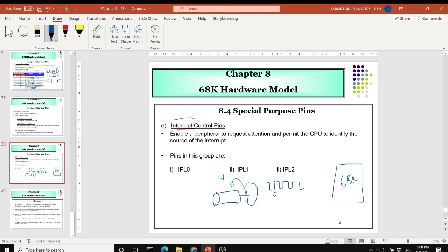One way of achieving this is by using an interrupt. The pulse is connected to the interrupt, so whenever there's a pulse, it interrupts your 68K and it counts the pulse. This is one application of interrupts that is normally used.